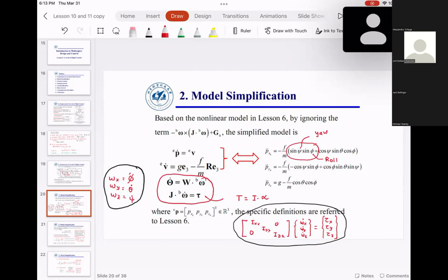And clearly the quadcopter cannot travel at 0 roll and 0 yaw. It needs to tilt and then it can go forward. Something like that you will have to take into account when you design the control algorithm.